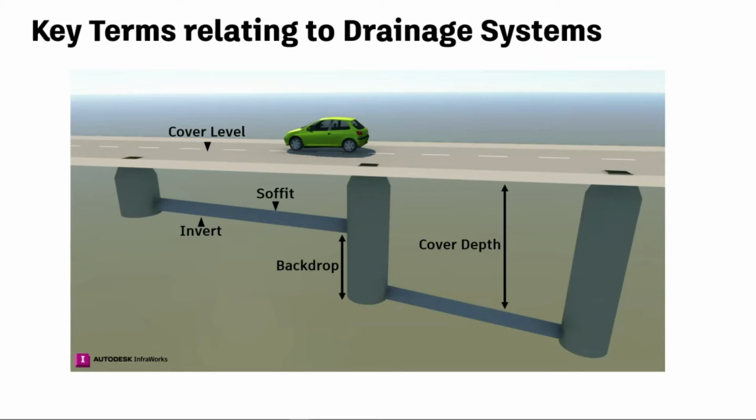It is also worth noting that throughout your career in drainage design, measurements are never in centimetres. Never mention centimetres again in your professional career. Up to 1 metre, you can use millimetres, so a pipe will be 375 millimetres in diameter, not 37.5 centimetres. Above 1 metre, you can either use millimetres or metres, so 1,200 millimetres or 1.2 metres diameter.